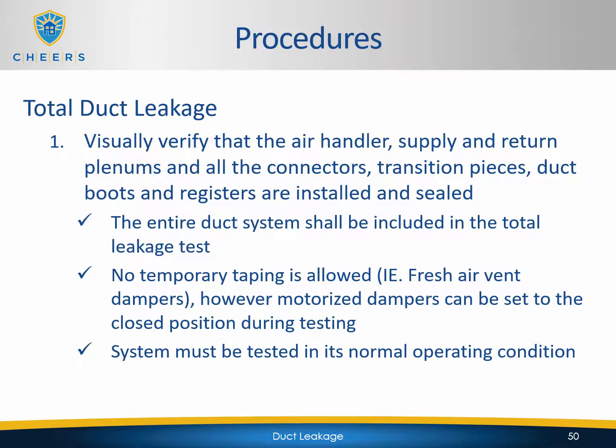There is no temporary taping allowed, for example, of fresh air vents or dampers. However, motorized dampers can be set to the closed position during testing. Ultimately, the system must be tested in its normal operating condition, however the system is going to be once the homeowner is actually using it.